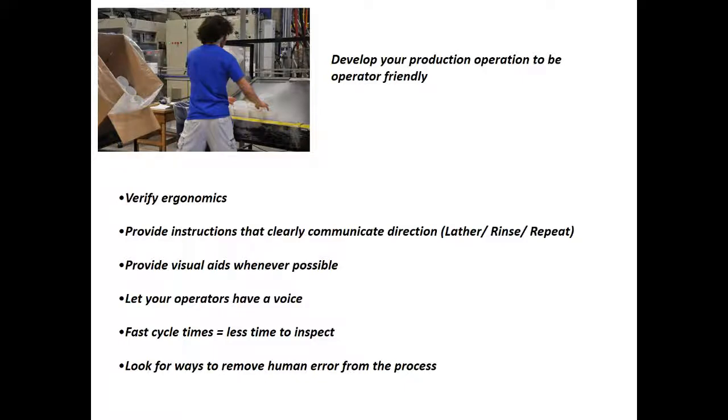Another, if you have recurring scrap events that are occurring, and you have samples of those defects, then you can put postings or samples of the reject at the press so that the operator has that available to them, and is aware of the situation.